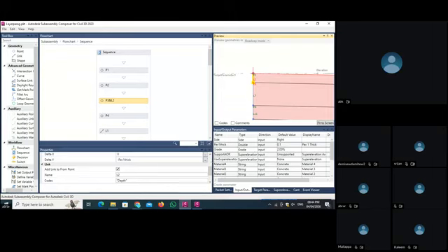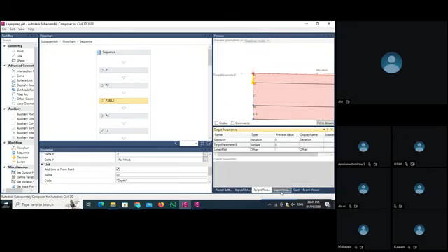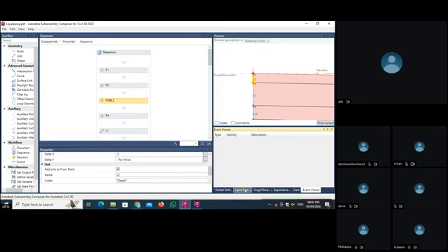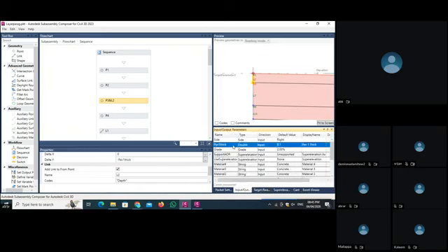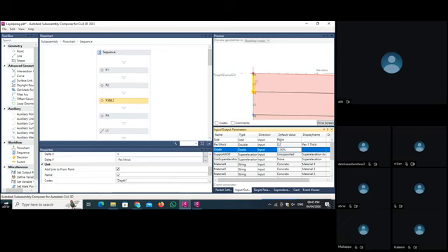As a link is here in the y-axis, we give the delta y value as minus pave 1 thick. And here are all the target parameters we have to create. See the pave 1 thickness is 0.1 right now. If I change the thickness here to 0.2 and press enter, automatically this width is changed. So I put it as 0.1 again. So if you fit the screen, then automatically this will set. So this is the sub-assembly composer.